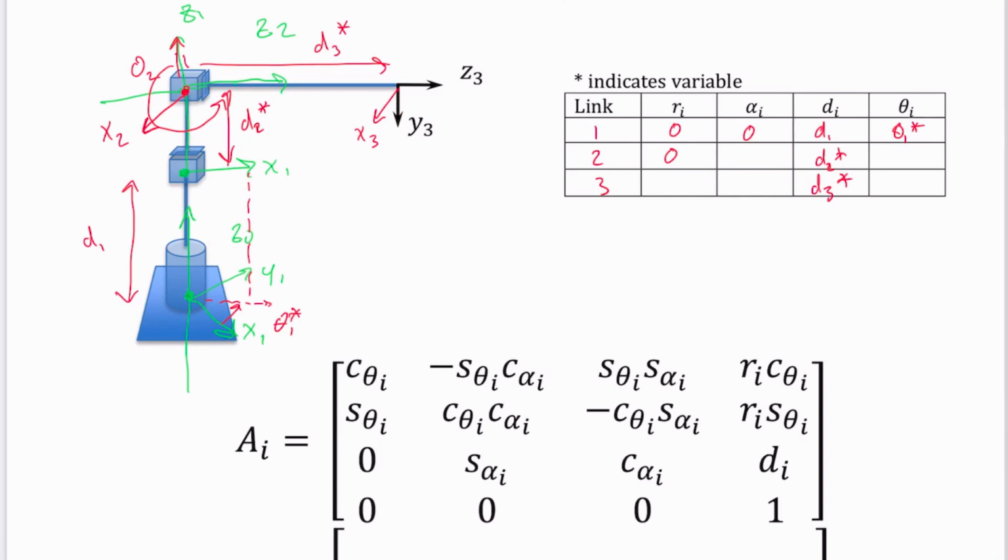I do have an alpha twist, which I said was either 270 degrees or negative 90 degrees. I've got my prismatic joint, and then I've got no rotation about my theta, so 0 degrees. Then my final third joint, again, these axes intersect, so I've got 0 here. My z-axes are parallel, so there's no change there, and there's no rotation.